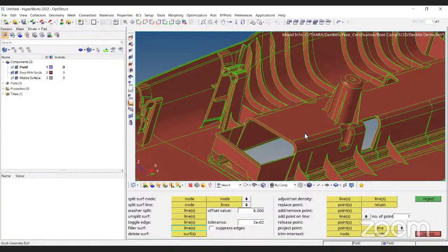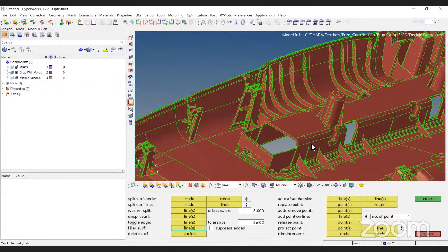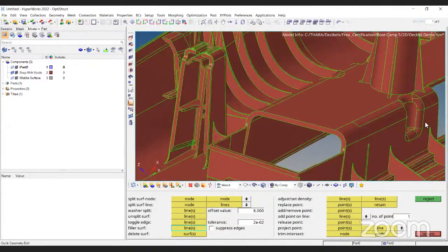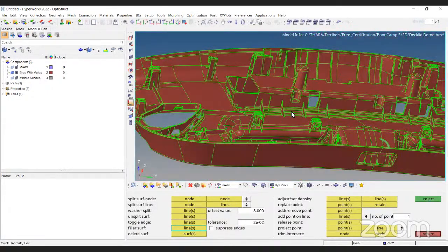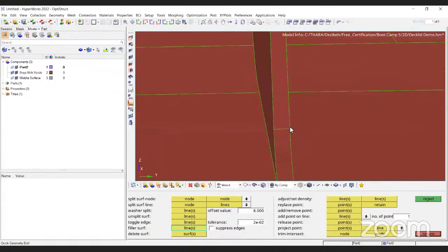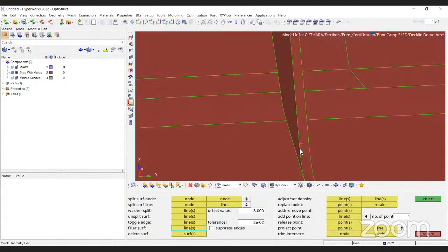When the thickness is very small, compared to the casting component. A casting component, in the sense, compare this decklid with the engine mounting component, where the engine looks very big. It looks like one box. For that component, we are not going to extract the mid surface, since the component is within a defined thickness. So for those components, we are going to define the thickness. So you can ask me, what is the thickness? See, this is called the thickness, or in your academics, we call it a width, the width of the rib. Here we call it the thickness of the rib.